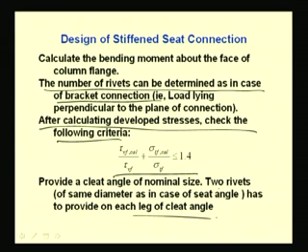is that the design of the seat angle is the same as in the case of unstiffened seat connections. Then the new thing is how to design the stiffener. For choosing the stiffener we have to follow this process, and this will be clear if we go through some example. Before going to the example, let me see how it looks like. Stiffened seat connection.